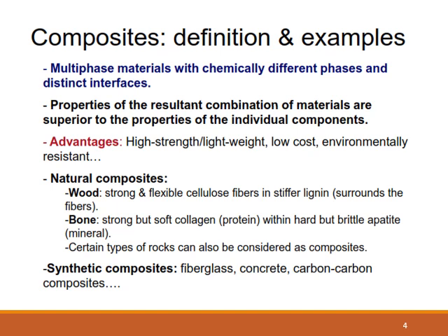So there are ways now that you can toughen a glass material by incorporating a fiber therein. So what it means is that even when the glass is struck by a load that is more than what it can bear, you can see it will crack, but it will not shatter. So that reinforcement allows it to have better properties. So this is a typical example.